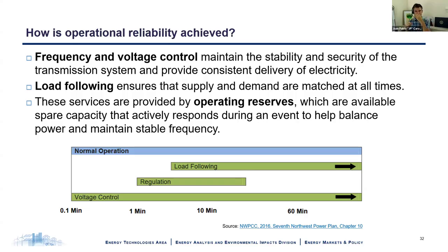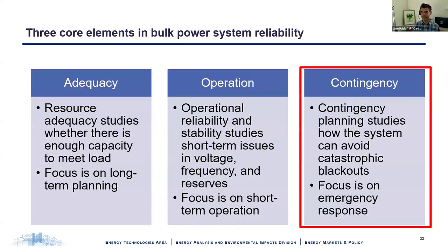And we need to program those inverter-based resources cleverly to simulate the same. But it's definitely doable. It's something that operators are learning how to do. So we don't have major issues here. But for example, a recent exception of this is the large blackout that occurred in Spain, in the Iberian Peninsula a few months ago, that you may have heard of. That was entirely an operational reliability issue. There was enough adequacy, but there were issues managing some of these frequency and voltage controls that led to separation of the entire country out of the European system.